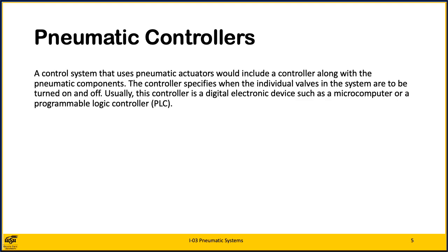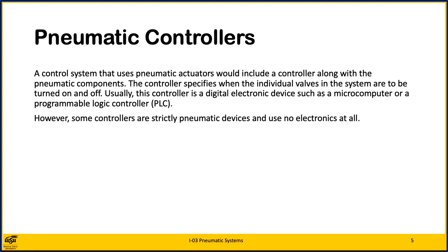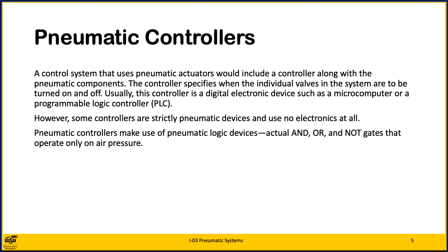A control system that uses pneumatic actuators would include a controller along with the pneumatic components. The controller specifies when the individual valves in the system are to be turned on and off. Usually, the controller is a digital electronic device, such as a microcomputer or a programmable logic controller, or PLC. However, some controllers are strictly pneumatic devices and use no electronics at all.